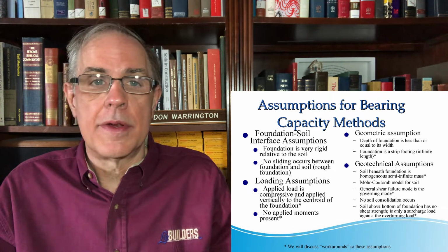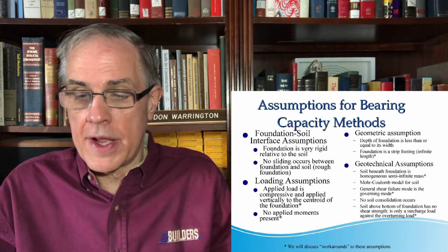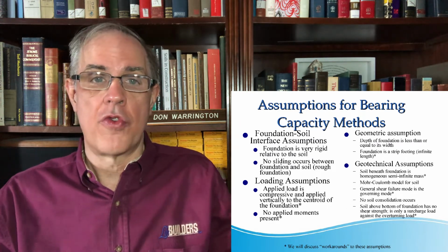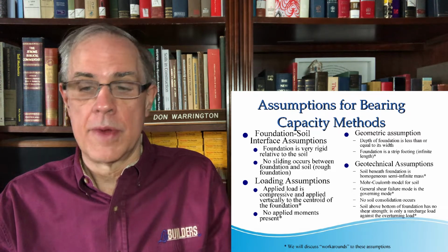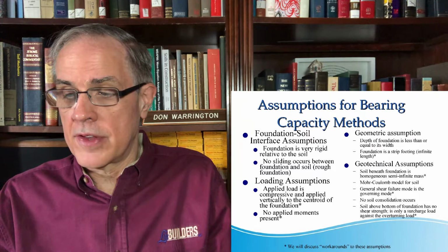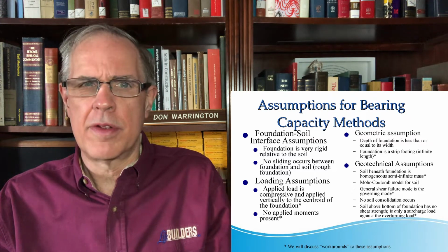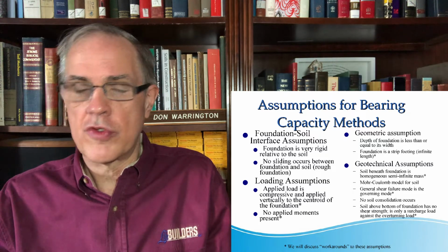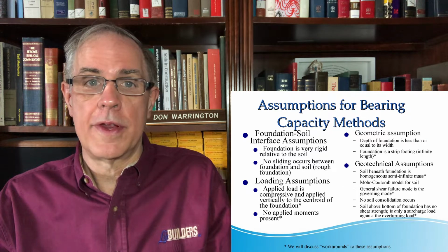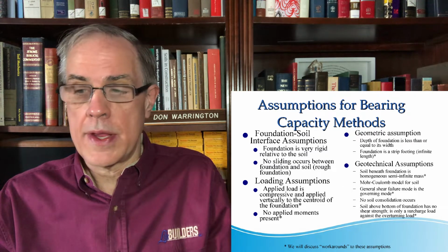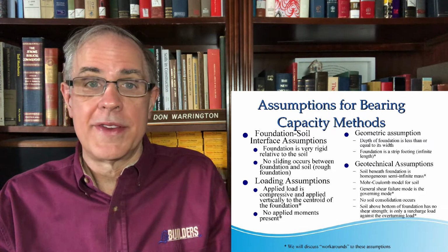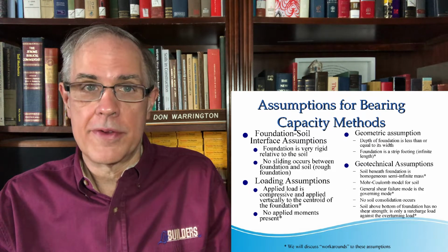The applied load is compressive and applied vertically at the centroid of the foundation, and it's uniform. In other words, it's a concentric load. There are no applied moments. The depth of the foundation is less than or equal to its width, which is typical for bearing capacity. The foundation is a strip footing. Bearing capacity theory was developed for strip footings, and then we extended it. We're going to talk about those extensions.